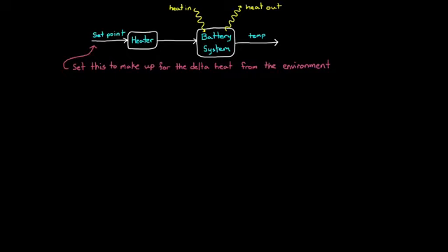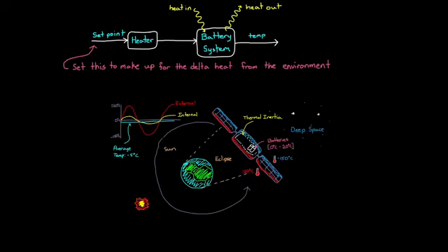With this design, if we're wrong about the outgoing or incoming thermal energy, then the battery temperature will be off from what we desire, and the controller will have no way to compensate for that error. It's a predetermined set point. Now, this might be a good approach if the system was going to operate in a well-controlled environment. However, that is not space, because the external environment is always changing.